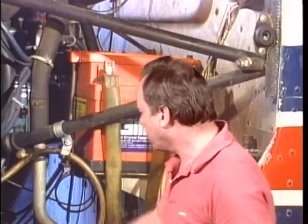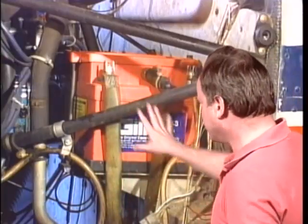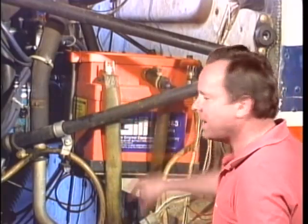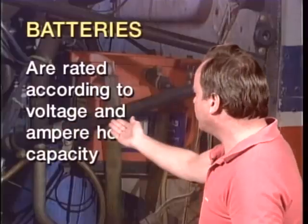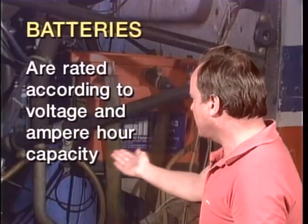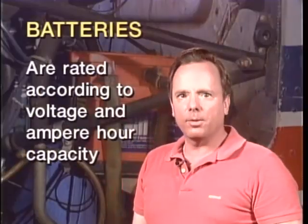Now, let's talk about aircraft batteries, called storage batteries, inside an aircraft. This is an example of a lead-acid storage battery inside an aircraft. And they will ask you a few questions on the FAA written exam about these batteries. Let's take a look at it. First of all, how are batteries rated? Well, they're rated according to voltage and ampere-hour capacity. How many amps can they put out for what period of time? And that's called ampere-hour capacity.